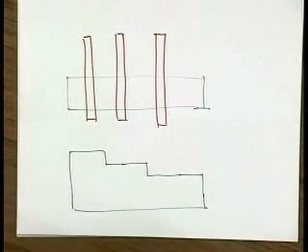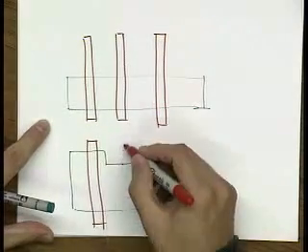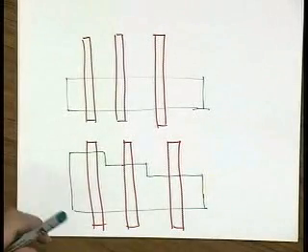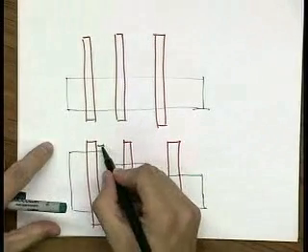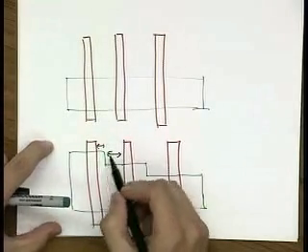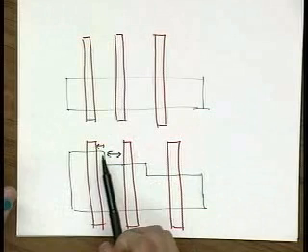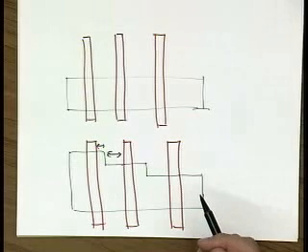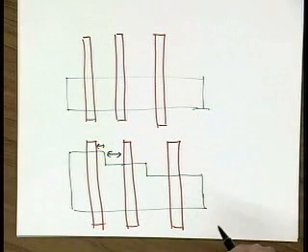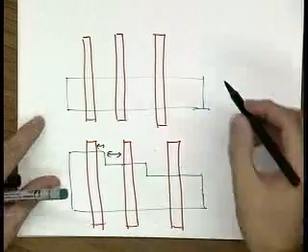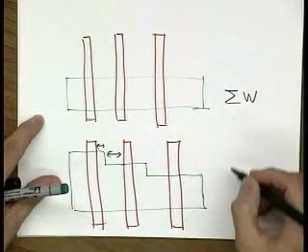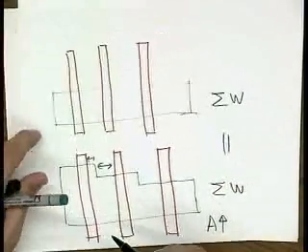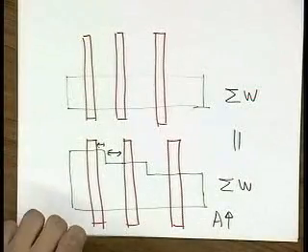Then I have to step down a little bit in diffusion, and then finally proceed with the last one. What this influences is that I'm going to end up with an overall wider cell, because I have all these constraints from the design rules that there should be enough spacing between diffusion and poly and so on. As a result, it buys you performance. It offers you better performance, certainly, but you have to pay a little bit of a price in area. For the same total overall sum of W, if you sum all the W's here and sum all the W's here, they're equal. But the area is a little bit increased because of these design rules. Okay.